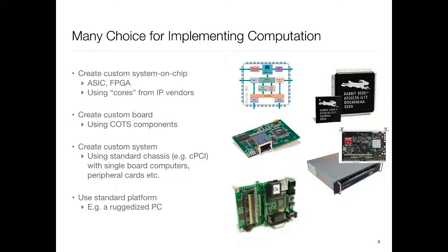There's another language called VHDL, and then there are a bunch of other languages which are even higher level, like SystemC and things like that. But the idea is that the design of hardware nowadays, the starting point is pretty much the way you think of software. You write a piece of code and then you go through a compilation process. It's just that the output of compilation, instead of being assembly code or object file or executable, is the layout of your chip or the layout of the FPGA.